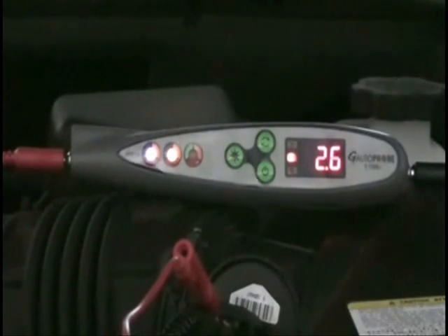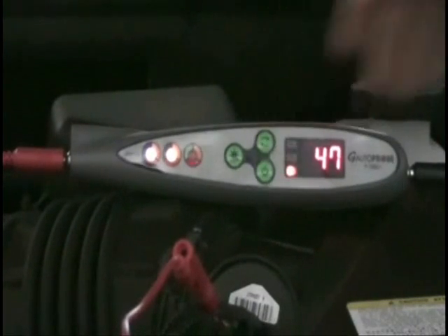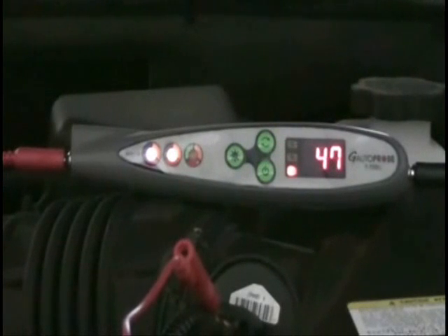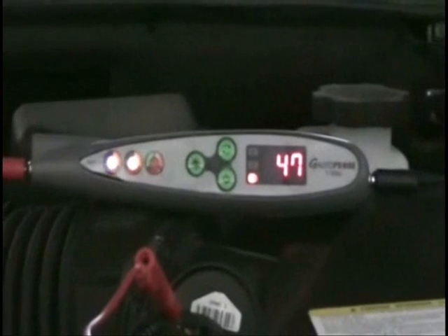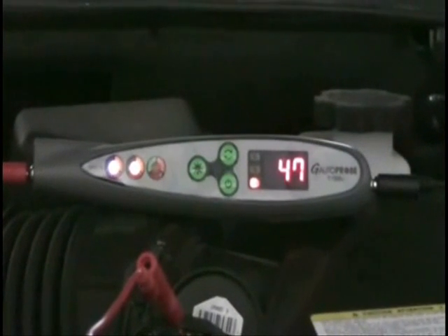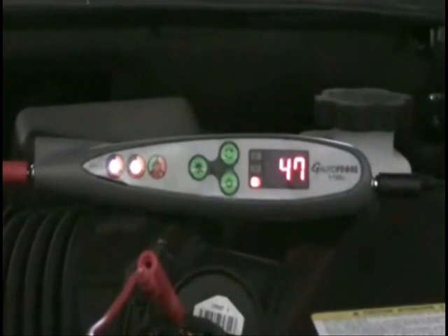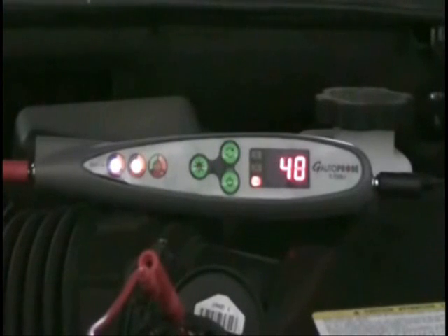Push the selector again and change the mode to duty cycle. Duty indicates the positive section in a pulse cycle in percentage terms. Let's say a pulse cycle is 100% and the positive section is the duty cycle. It shows 47% duty cycle of airflow sensor pulse. Often the positive section of duty cycle is called positive duty, while the other section is called negative duty.